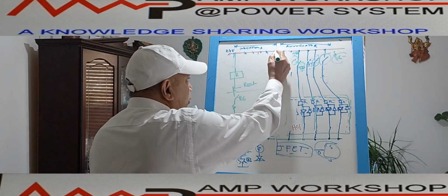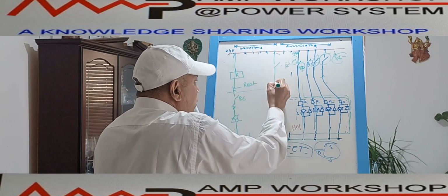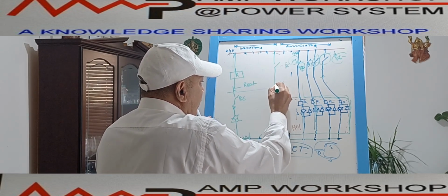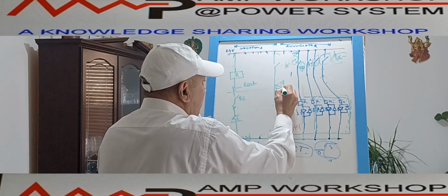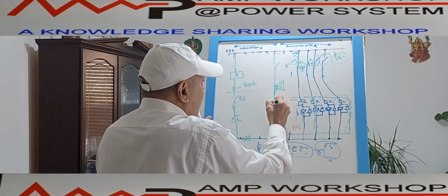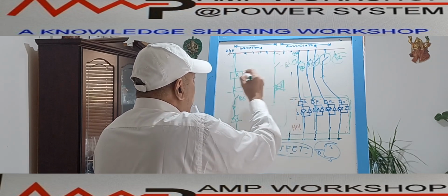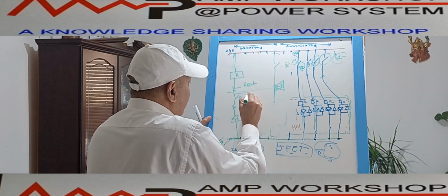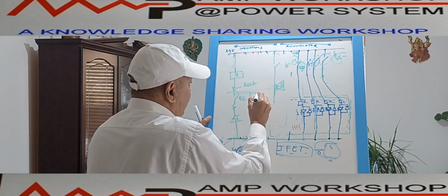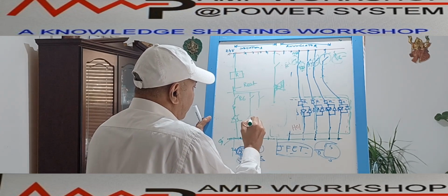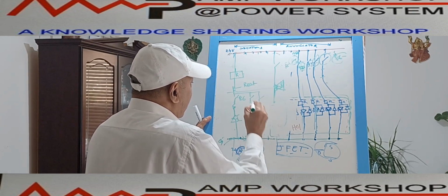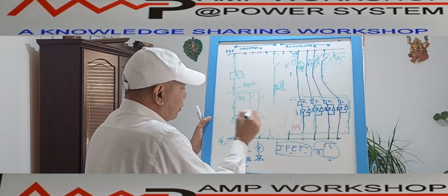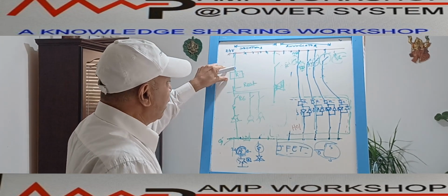This R relay contact, what we do, we put a horn over here. This is our horn. Suppose this is one parameter; similarly, we can connect multiple parameters over here. So this is another lamp. As we have a multiple number of functions, we can use this way. All these functions we can put over here, but through a relay.